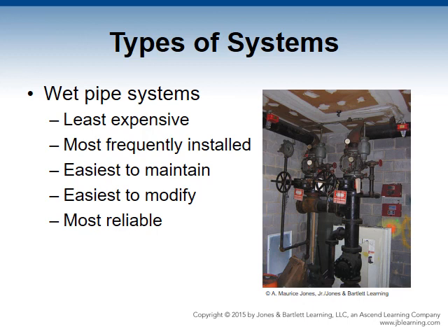They are preferred to other types because water is in the pipe at all times, so the water flow is immediate after the sprinkler head is activated. It should only be installed in environments that are not prone to freezing.